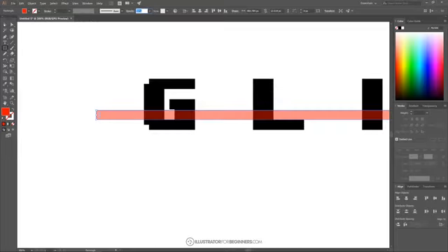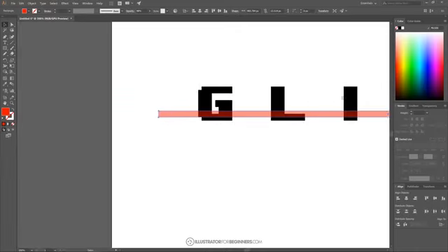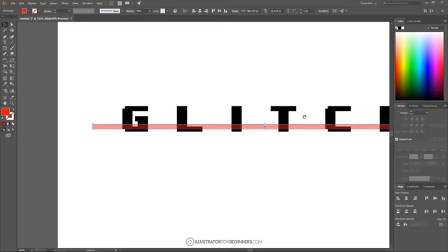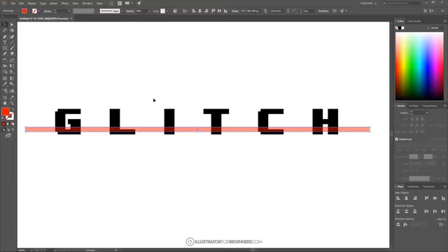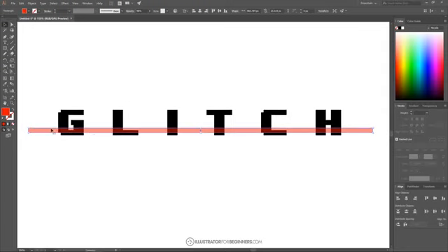And I'm going to grab the Select tool. I'm going to hold Control on the keyboard and grab this node right here and then just snap it to this node right there. And let me just move that back over. I'm going to hold Shift so it locks onto the vertical axis. And let me zoom out a little bit so I can see what I'm working with here and see where that rectangle is aligned. To move the page around, I'm just pressing down the space bar and then clicking and dragging. We want this rectangle going over the entire text object like that.